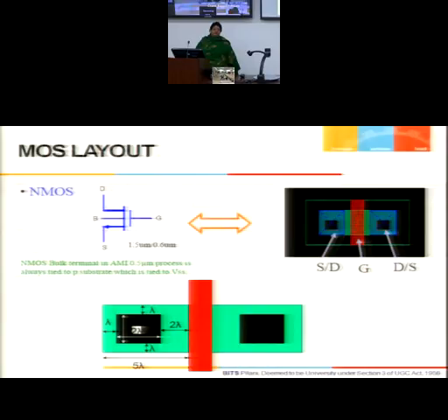Okay. Now if I know, total capacitances are proportional to Cj area plus Cj side wall. So if I have a certain Cj area, that would be multiplied by 80 into 5 lambda square. 80 into 5 gives you 400 lambda square. Cj0, that is the area component, multiplied by 400 lambda square. Please visualize.